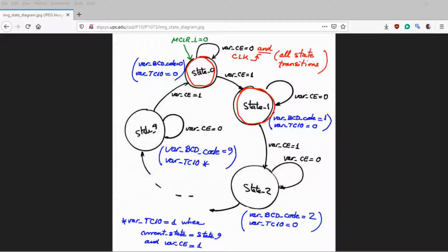And then you can imagine that you can stay in the same state, or you can go to the next, depending on the signals that are advancing the next state logic. Okay, this time, however, the big difference is that the signals are not anymore voltages. What you see here is not a voltage anymore, but a variable in the RAM memory. That is what you see.